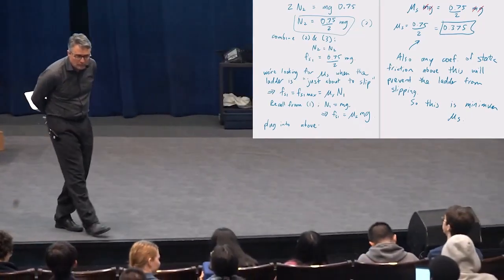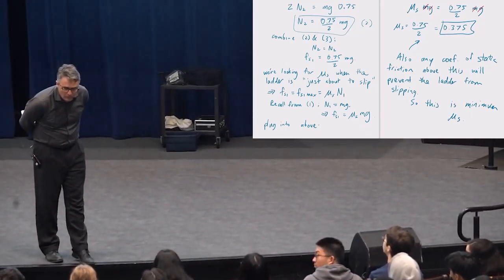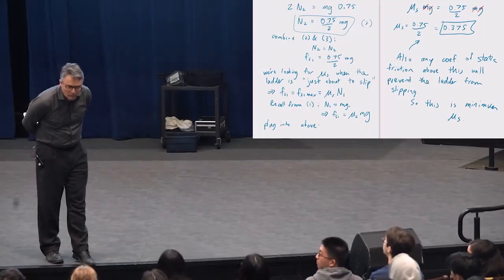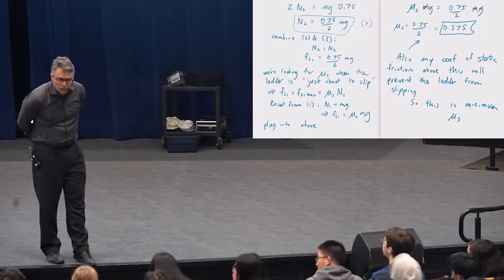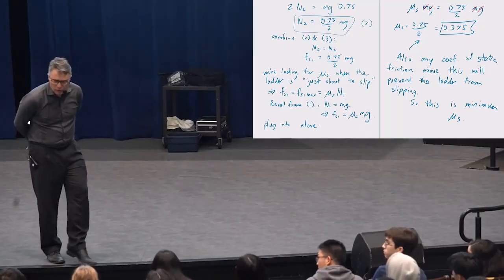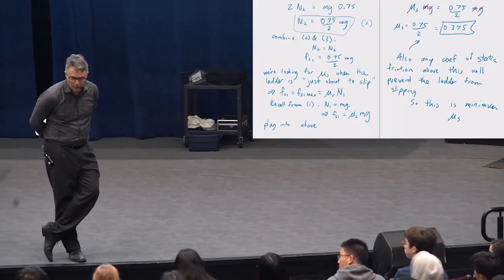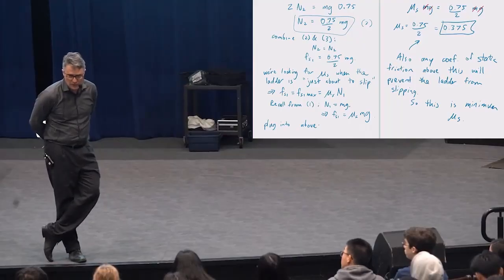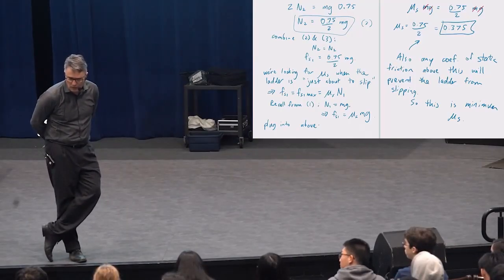I was wondering, why is N2 not 0 if it goes through the pivot point? And why is N1 0 if it doesn't go through the pivot point? N1 and N2 are both non-zero normal forces, but the torque from those forces is 0 if the force line goes through the pivot you've chosen, right?